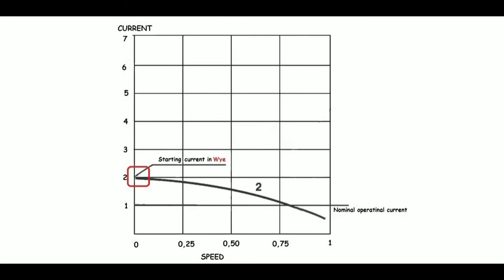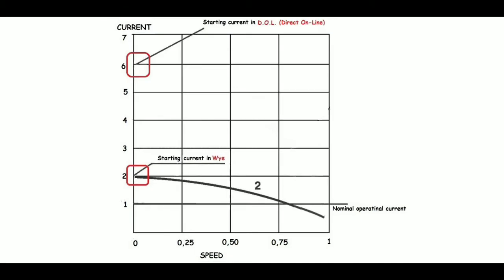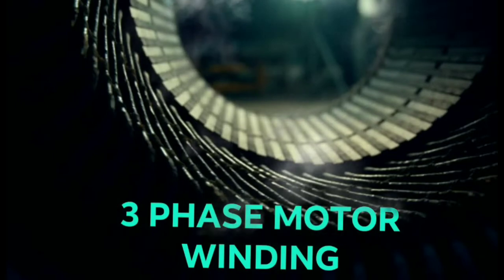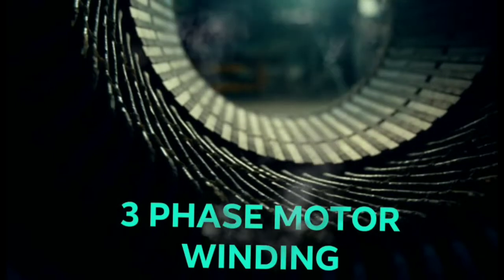During the Y starting condition, it has current approximately 3 times less than the current if it is connected using only the across-the-line electric motor, also called the direct online electric motor control. Wye-Delta Electric Motor Control is also used to avoid the persistent tripping of the overload relay, which may damage the motor winding if repeatedly started several times.